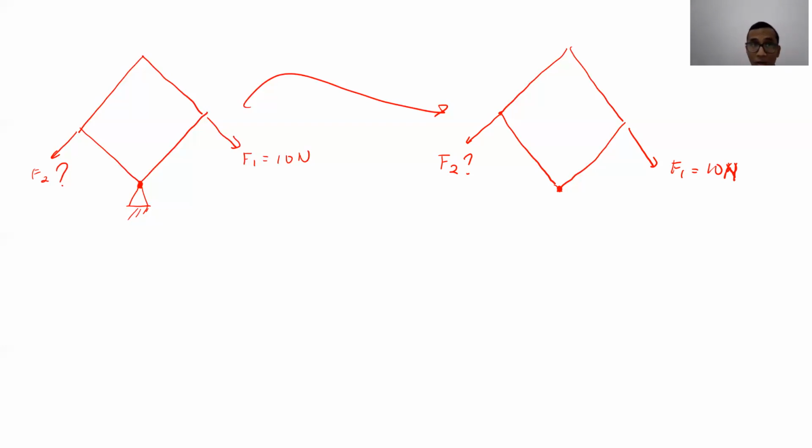perpendicular to each other. When you have a pin like this, remember, a pin works like a hinge on your door. So basically, it restrains the movement in X and Y direction.